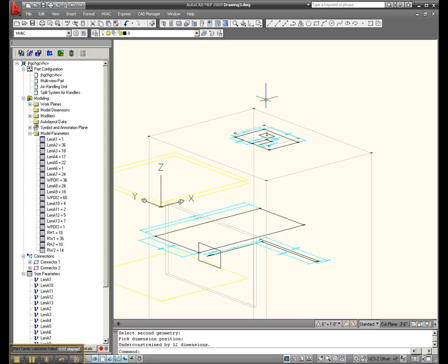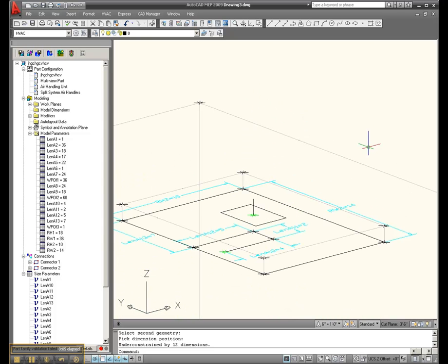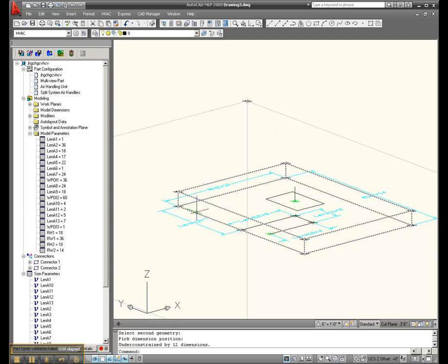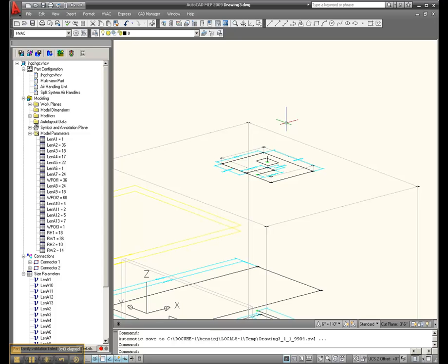Okay, something else to notice real quick, I just want to point out since we're learning here. We used a start profile and an end profile here, and they happen to be the same profile. But if you ever want to make a transition like a duct fitting, you can always do a rectangular profile on bottom, a round one on top, or a big rectangle on bottom and a smaller rectangle on top, between two work planes, and use the transition to make any shape transition you want. So the profiles don't have to be the same shape or dimension. So just something to note.